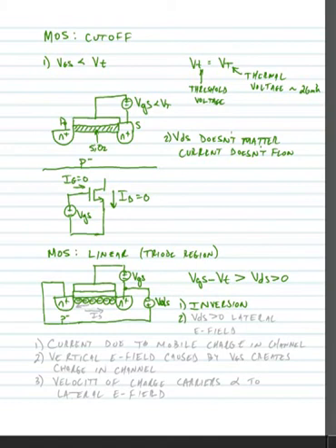If we start to draw enough carriers up and then increase VDS to be above 0, a lateral E field causes a current to flow. In other words, it causes these electrons to be moved towards the drain, meaning that we have a positive drain current flowing between the drain and the source.